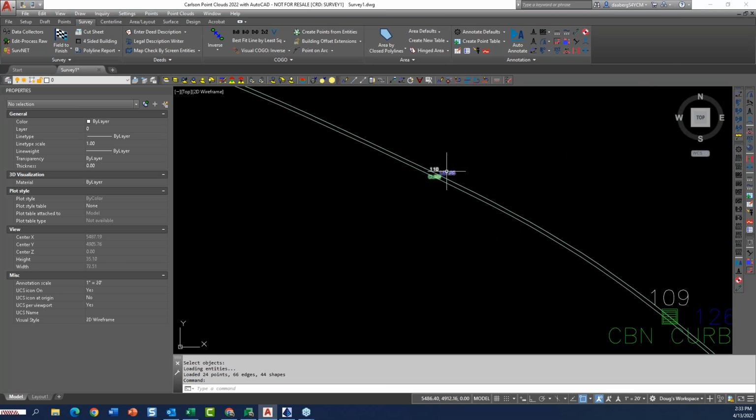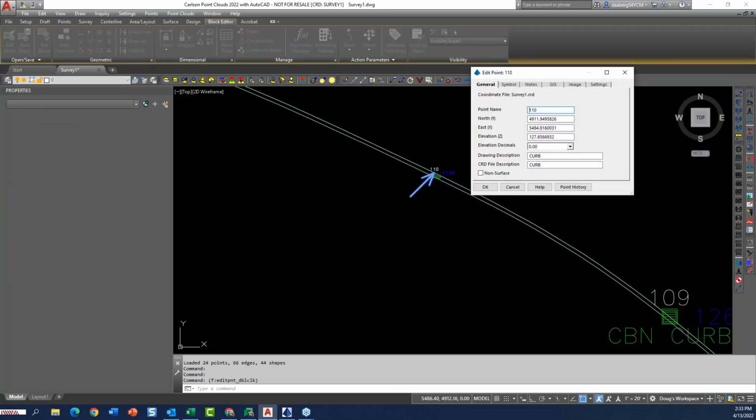It's the point right here, the curb is knocked down and drops to only 2/10 vertically. So all I have to do is add in the vertical offset, because that's the only one that changed. Again, it's consistently half a foot in width, but the height changed. You could conceivably do this on every shot, but again, it might be quicker to shoot both.